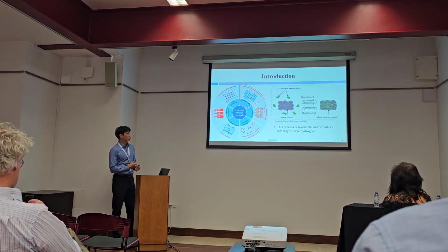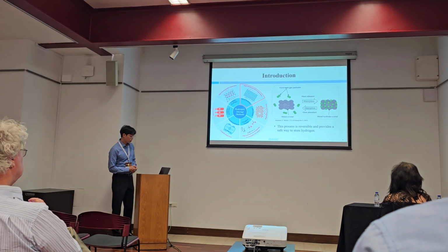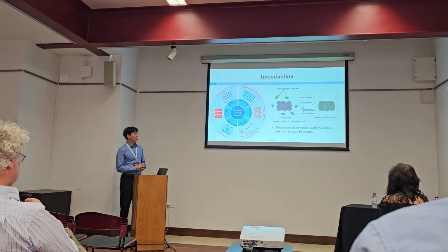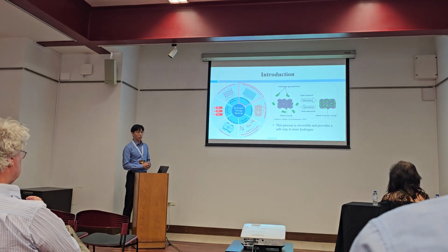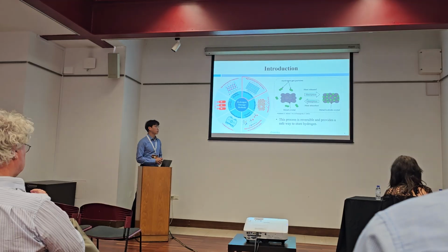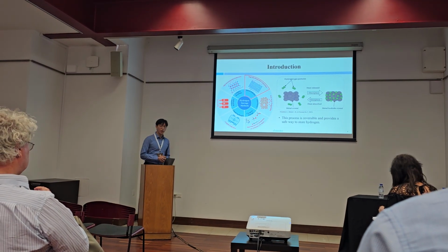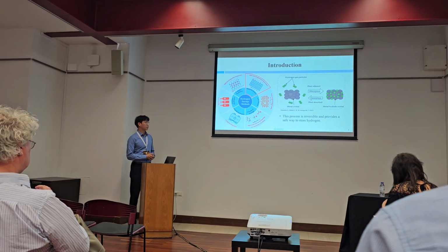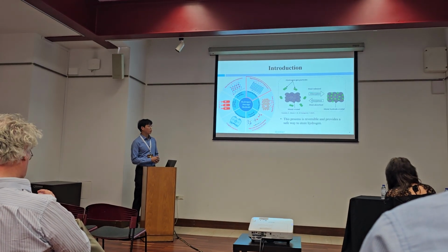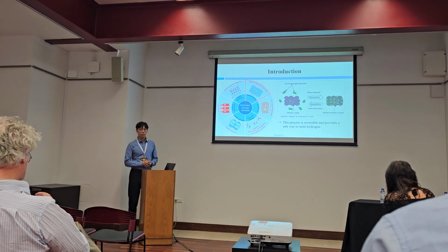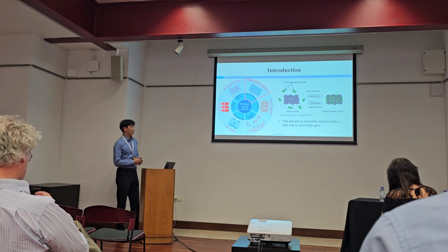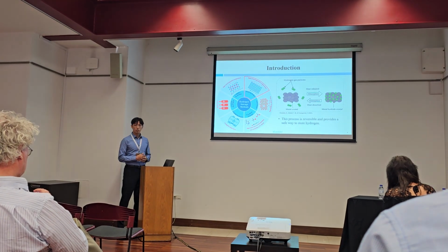Metal hydride works through a simple process. Hydrogen gas particles are first absorbed into the metal crystal. In this process, heat is released. When we need hydrogen back, we apply heat, and the hydrogen atoms dissolve from the metal hydride crystal. This process is reversible and provides a safe way to store hydrogen.